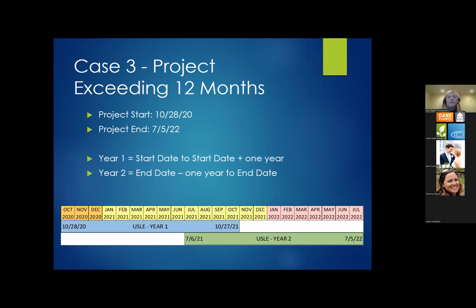For example, if we had an 18-month construction project, if that project was modeled at discharging 2 tons per acre in the first 6 months, 3 tons per acre in the second 6 months, and then another 3 tons in the final 6 months, then the project won't be in compliance because you're going over the 5 tons per acre per year.